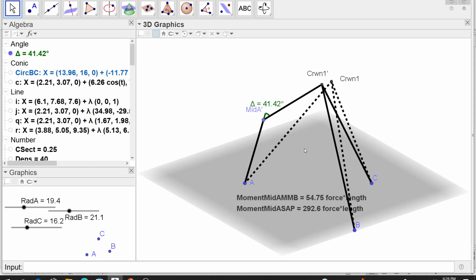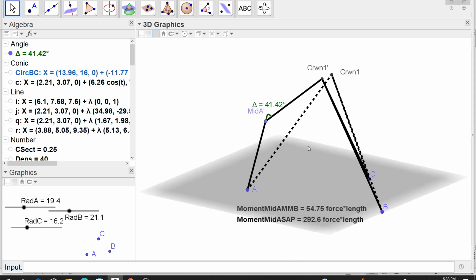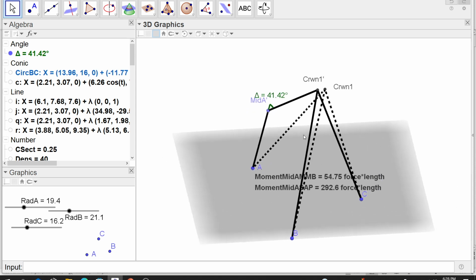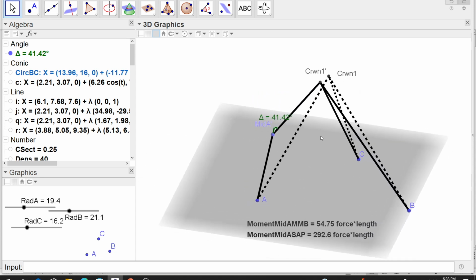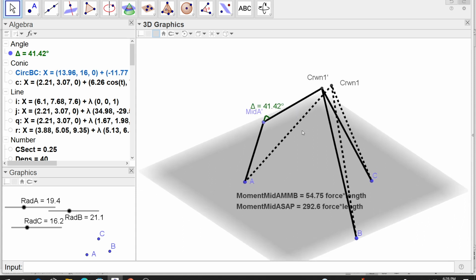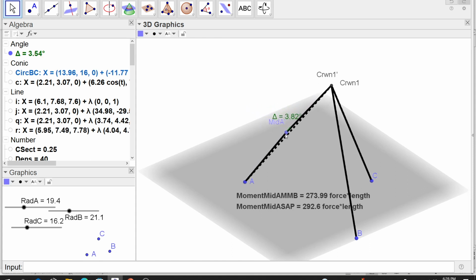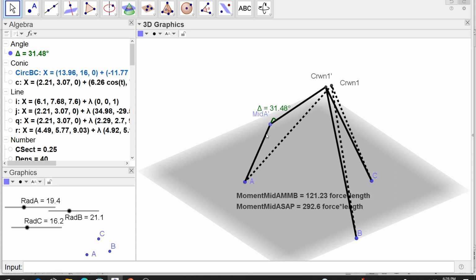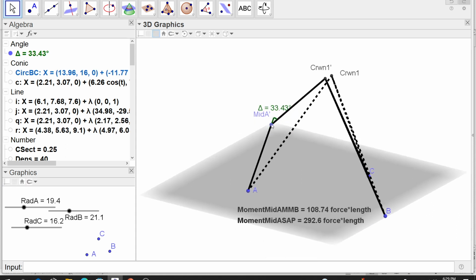This is a fun, quick tutorial on getting the bending moment at some cut in any of the members of a space truss or a space frame, I guess, because you must question why on earth there would be bending in a truss. If the loads are applied to the nodes, there is no bending. However, self-weight. If self-weight is present, as it is in your structures, then bending will occur.